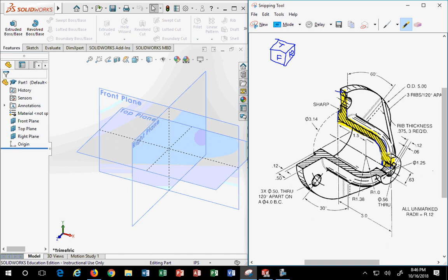Meaning, your basic shape, that entire outline, is what will revolve first, but any holes are done separately, which means I'm not including this feature down here, this hole, this gap over here. We're not going to account for it when we make this object in the basic sketch. We're building the whole thing without holes in mind.